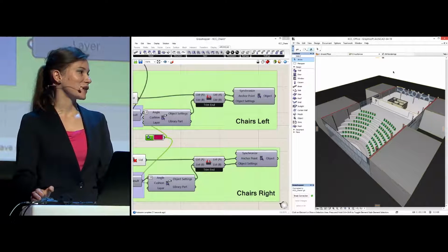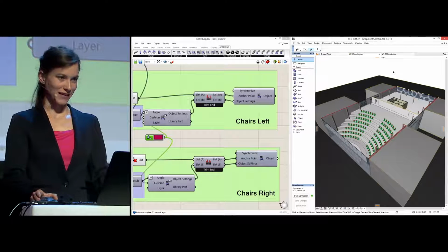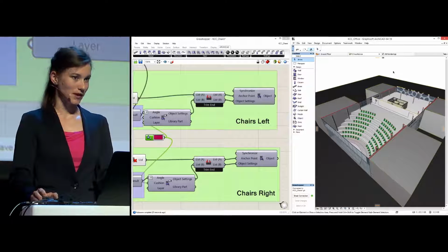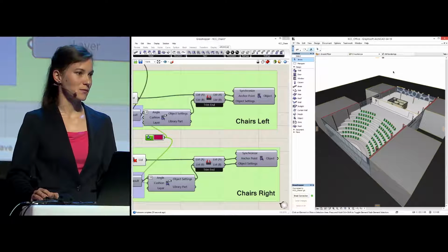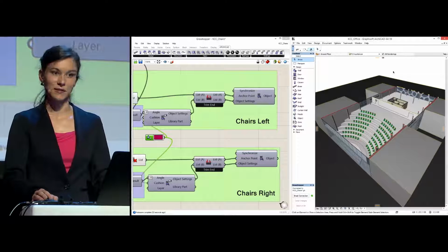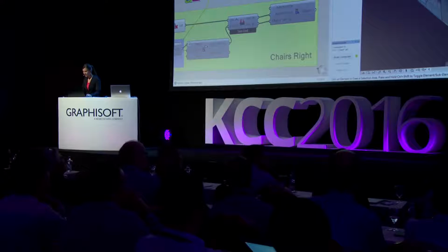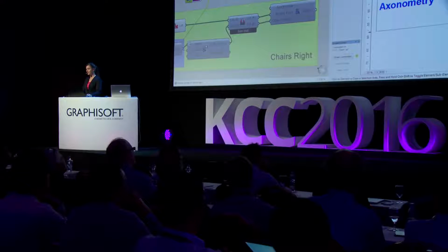Since we're architects, we need to keep an eye on data from the earliest phase of design. In this case, we need to know exactly how many people can fit into this room. Since we are building here a full-fledged BIM model, this information is available automatically. We only need to open the schedule and check the number. It's 118 now. It won't be enough. The clients want more.